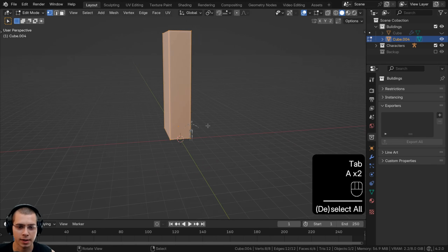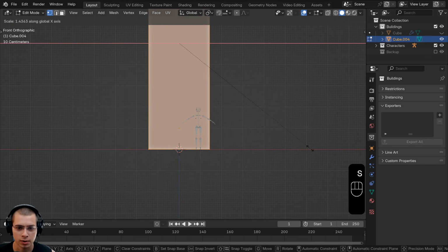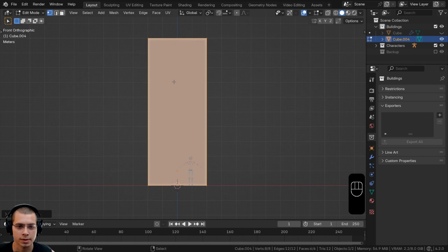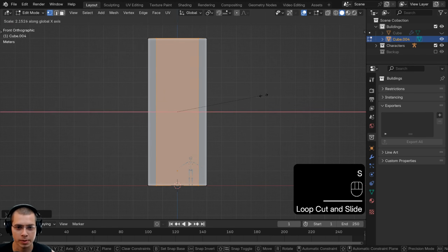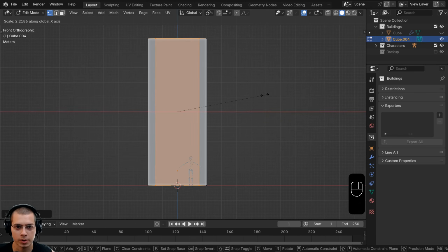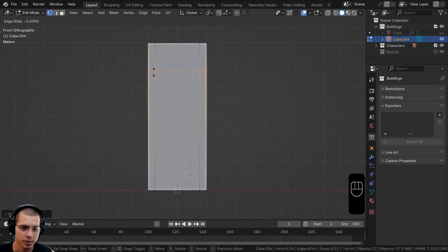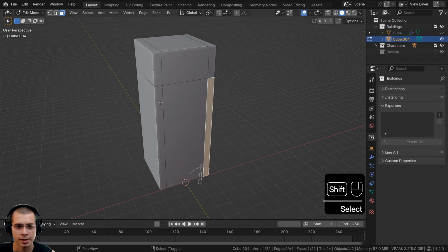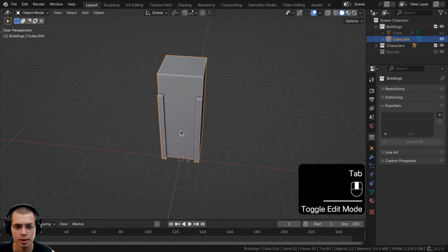And then we're going to select everything again in edit mode, and I want to scale it up so that there's 1 more grid on each side, so it's 4 grids long. So we'll scale it up on the Y, just like that, so it's 4 long. So in edit mode, I'm going to add some pillars, which are going to be on each side. So I'll add a loop cut, and I'll scroll my mouse wheel, left click and right click, and then we can scale these loops out a bit so that they're farther away from each other. We'll just make it about that high, and then I'll add another loop cut, and this one we're going to bring up here, but we're going to stick right about here so that it's 2 grids down from the very top. So we'll now go to the face select. We're just going to select these 2 faces, and we'll extrude them out a bit so that we kind of have those 2 little pillars there, make it about that far out.